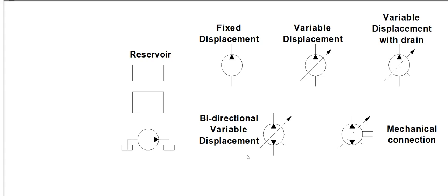So inside the pump itself, there would be a swash plate that would go over center and then go in the opposite direction. Again, we don't stop the pump and spin it backwards mechanically. It's always spinning in the same direction mechanically. We just, inside the pump, can switch which port is going to be our inlet and which one is going to be our outlet.